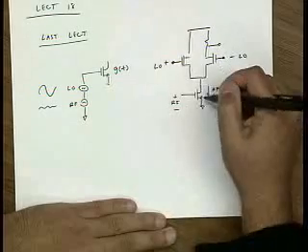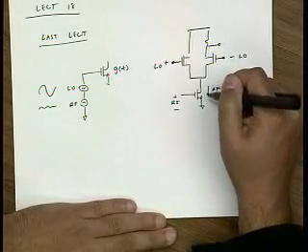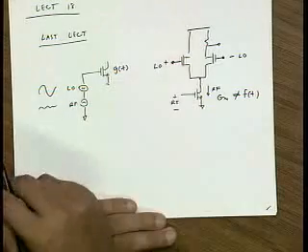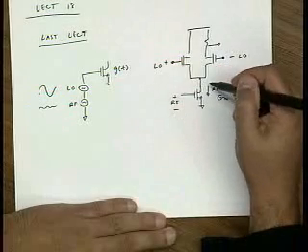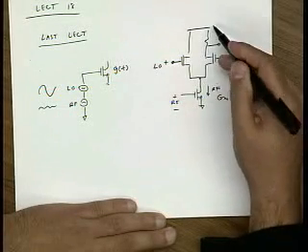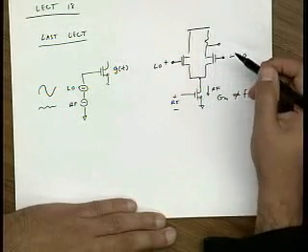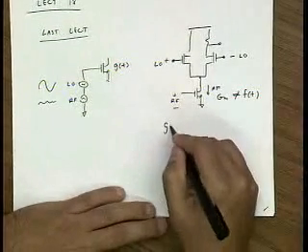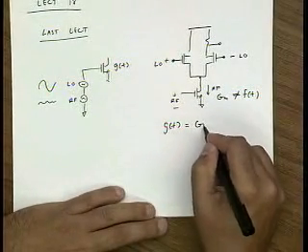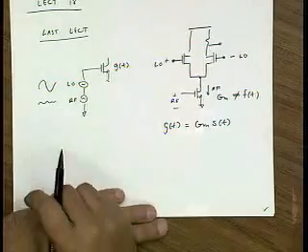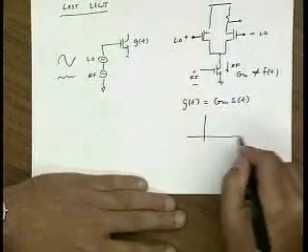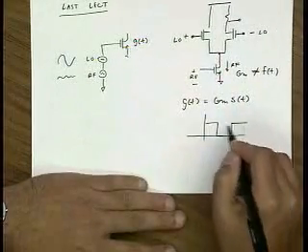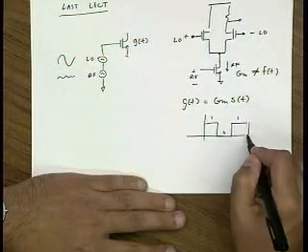And basically on the positive LO cycle, we take our RF current, we dump it to supply. On the negative LO cycle, we take our current and we dump it to our load. And so effectively, the total transconductance is a constant times some switching function. And in this case, ideally, the switching function will be 1, 0, 1, 0.